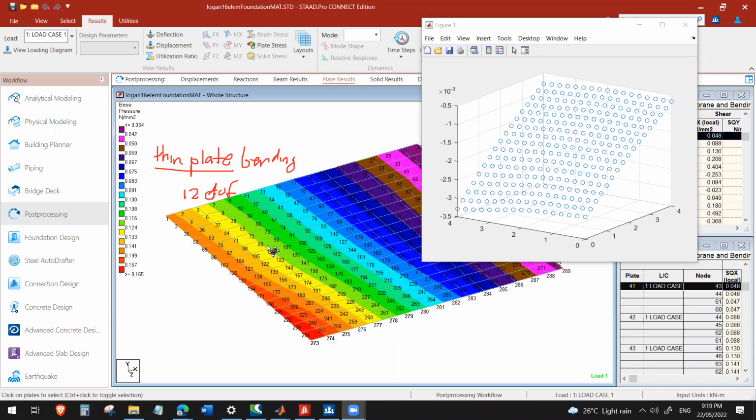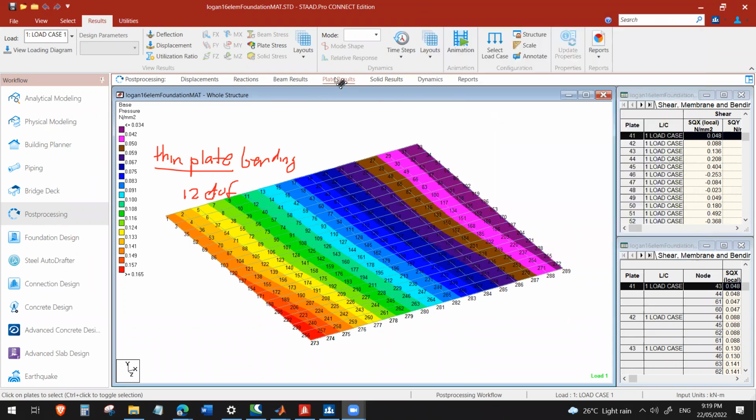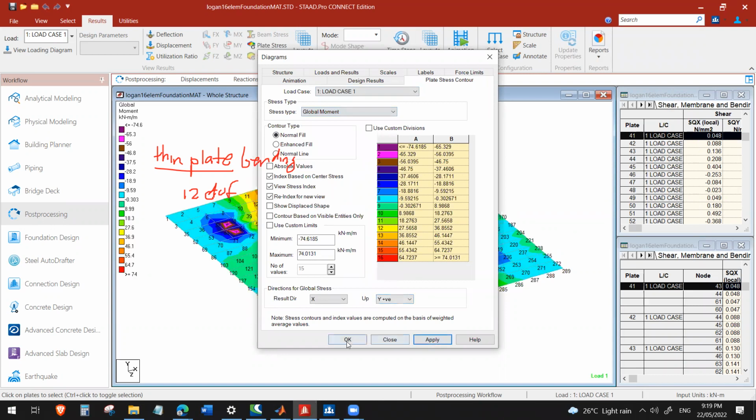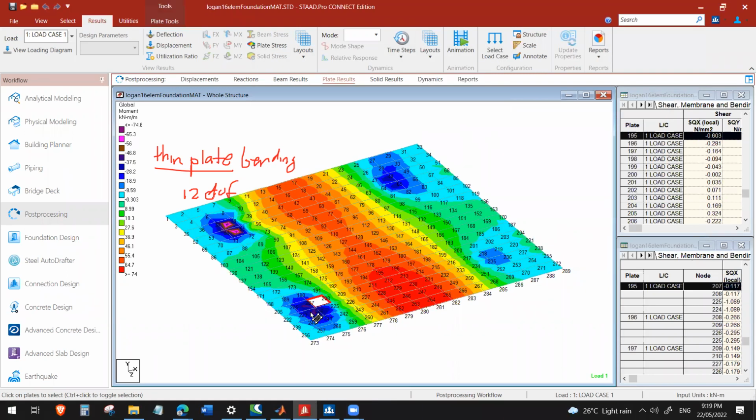And again, when you wanted to design the rebar for this, remember, you just have to call out the moment and use that to design your rebar. Simply, when you have the moment, you can use this formula, R = Mu/(phi b d squared), wherein you can get the R, and then you can get the rho and the As required for the design. Okay,